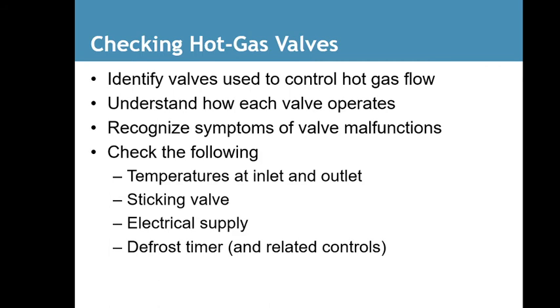Check hot gas valves. Identify the valve used to control hot gas flow. Understand how each valve operates. Recognize symptoms of valve malfunction. Check the following: temperature at inlet and outlet, sticky valves, electric supply, defrost timer.